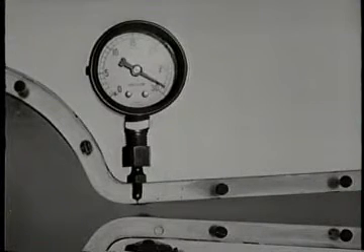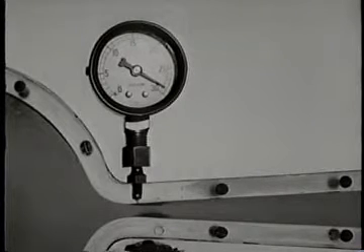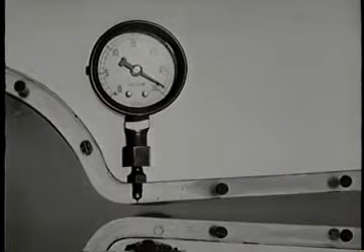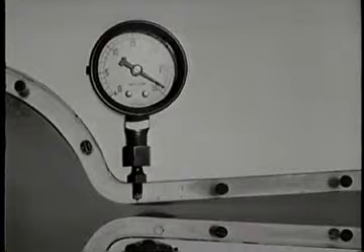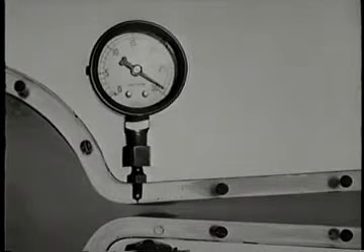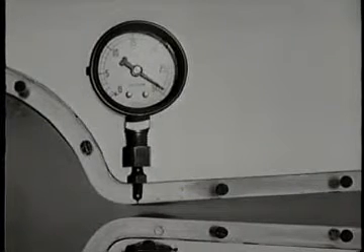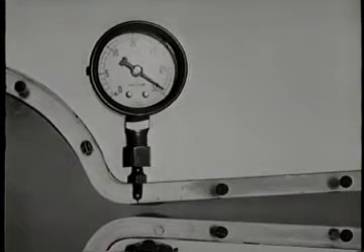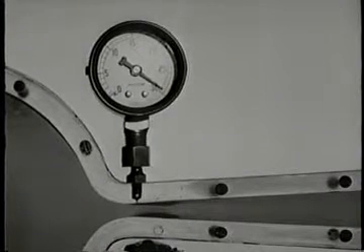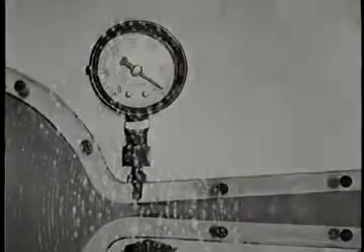The water changes to steam, and the subsequent collapse of the bubbles, which you can hear, creates enormous stresses in the wall. Mechanical stresses owing to the implosive collapse of cavitation bubbles on a surface do great damage to hydraulic machinery and to marine propellers.